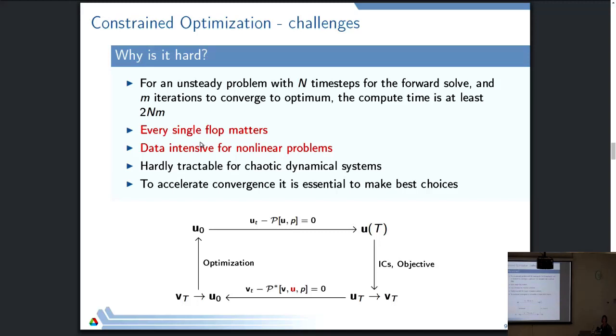We did an error analysis. Okay, so for SEM you're never going to have a nice line. It doesn't have algebraic convergence, it has spectral convergence. So you need to go into spectral space and look at the coefficients and their decay, and then from there say what your loss is. So yes, true. The sharper the gradient, the lower the accuracy. That is a fact. When it comes to shock capturing, yes, spectral element method is not totally suitable.